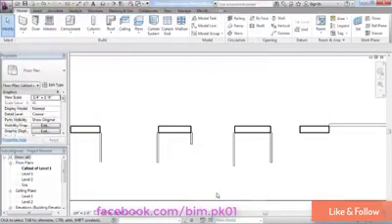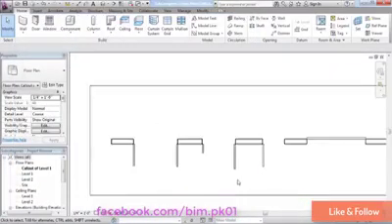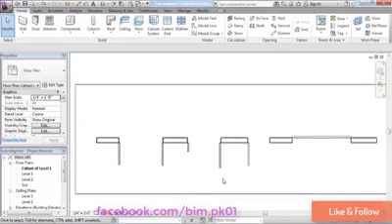Now that seems a little odd to me in a plan drawing, and therein lies the challenge that we have with subcategories. Despite everyone's best intentions to make things more flexible, more universal, and more global, if they're not planned out very carefully, you can get into problems. You can have redundant subcategories, you can have categories that aren't named very well, and so this gets into the realm of CAD standards and BIM standards and being very careful about the way that we assign these things.